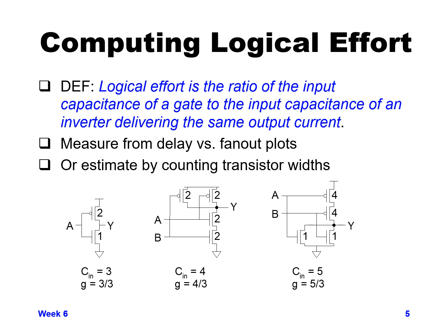So in reality, if you really wanted to get the absolute best value for your logical effort, you would actually measure your input delay switching to your output delay switching and figure out what the logical effort is by plotting those values versus fan out. But it turns out this type of estimate that we're doing by counting our transistor widths is a good back of the envelope calculation, and so that's what we're going to be going with, something that's relatively easy to do and doesn't require a lot of designer effort and gives us pretty close to the right answer. So close enough for what we're trying to do without taking too much of your time and turning it into a research project on its own.